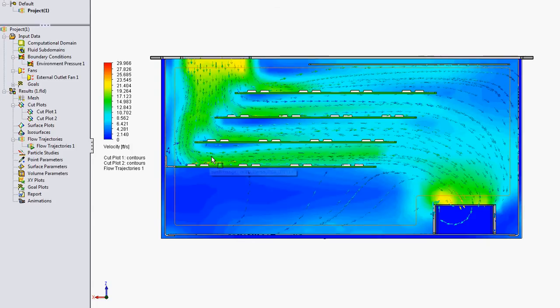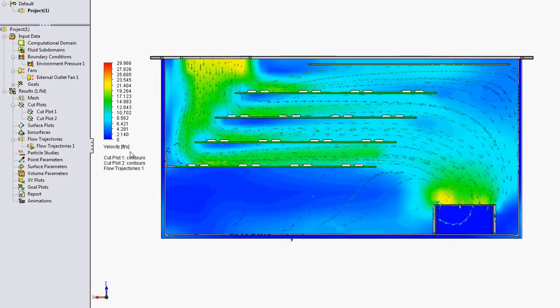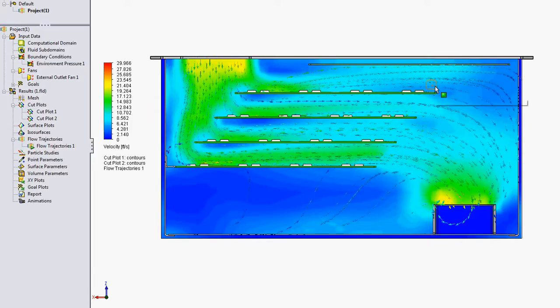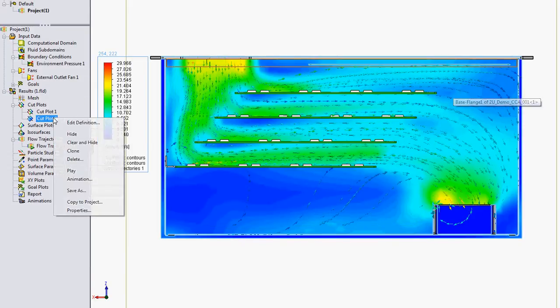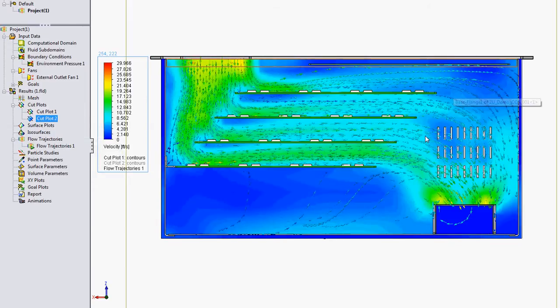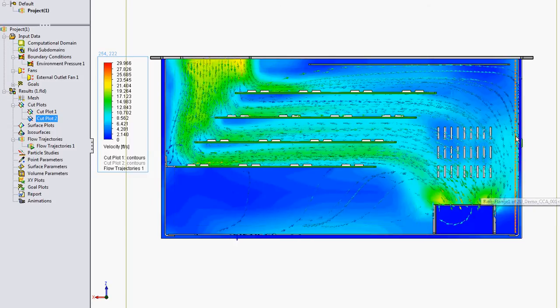What I'm trying to do is maximize linear flow velocity, which is what you see here, feet per second, over these CCAs, over the tops of the CCAs where you have FETs, and then bring in the air once it goes over those, keep the flow velocity up over the heat sink so that we're making sure that the processor is getting good cooling airflow there.